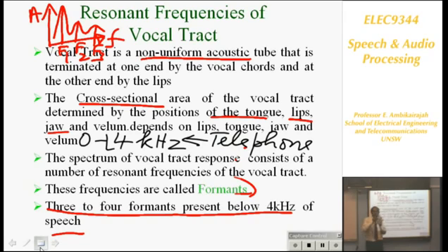That means if you measure all the frequencies in speech, you get about 7 kilohertz. So you are actually hearing 7 kilohertz bandwidth. But over the telephone, we filter them and keep it as 4 kilohertz so that you can sample at 8 kilohertz. Okay? For wideband speech like ISDN, you must have the wider bandwidth.